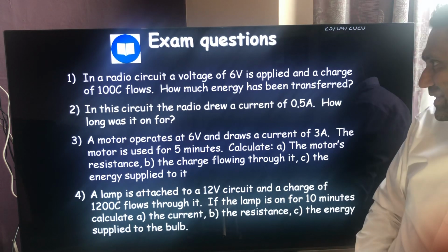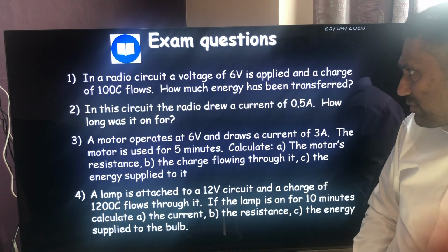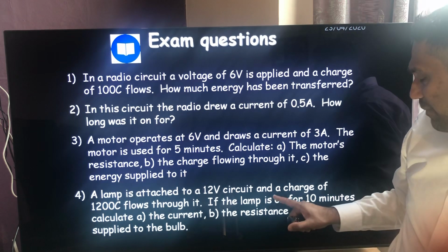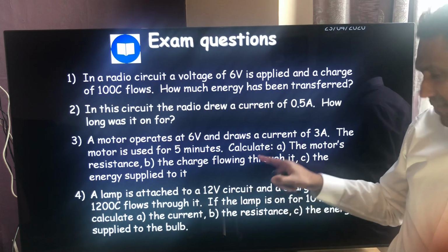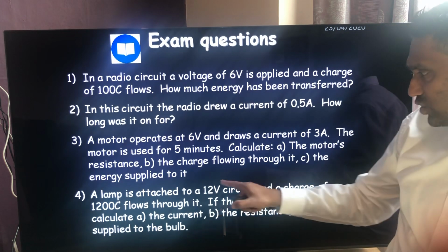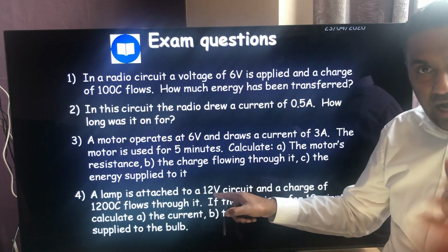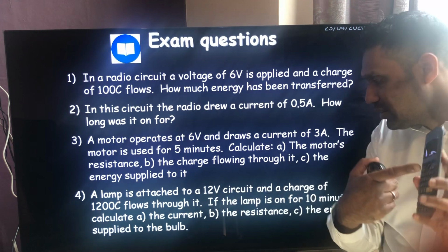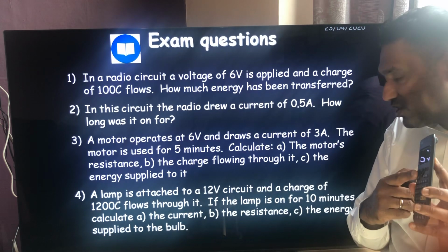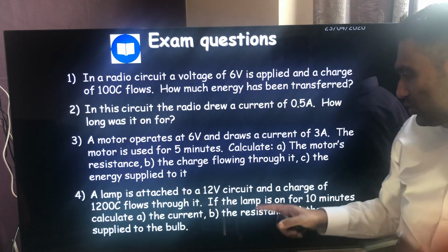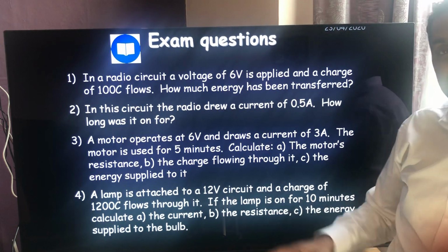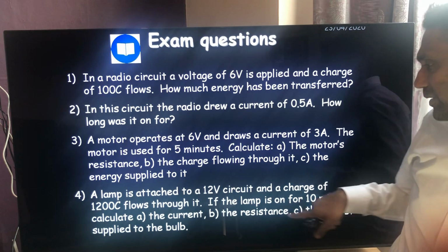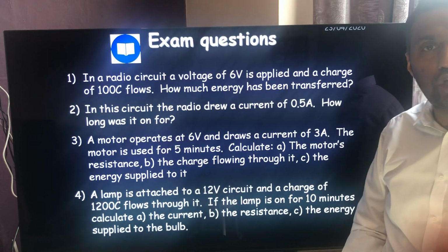What's the resistance in this circuit? Well, the resistance, remember we did it from V equals IR. So V equals IR. My resistance R is going to be V divided by I. Well, I've got 12 volts here. I've just worked out my I, which was 2. So it's 12 divided by 2 amps from the previous part of the question. So 12 divided by 2 equals 6. So the resistance is 6 ohms. Okay, 6 ohms.